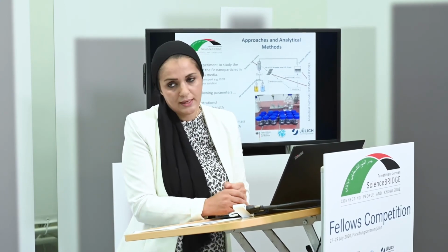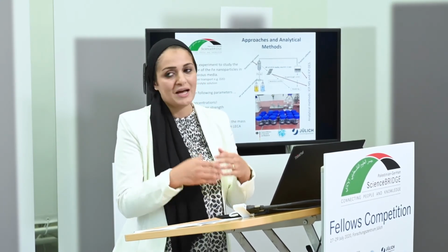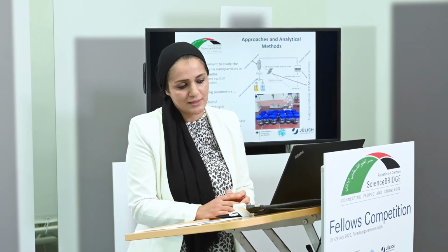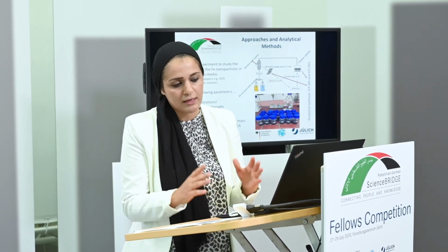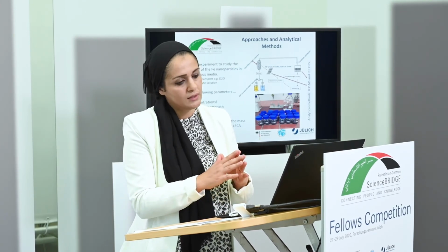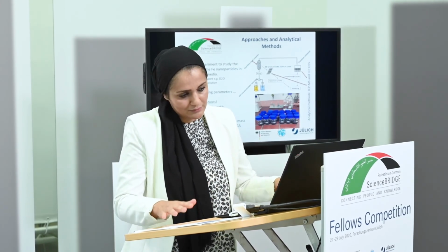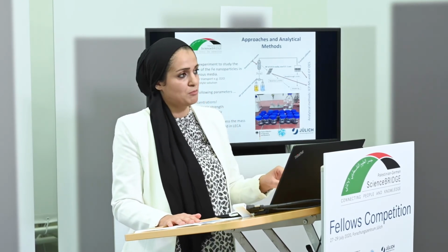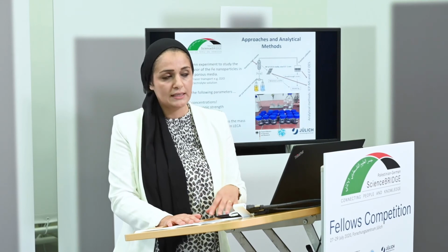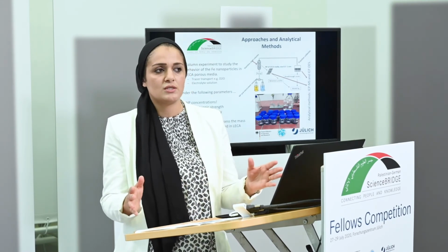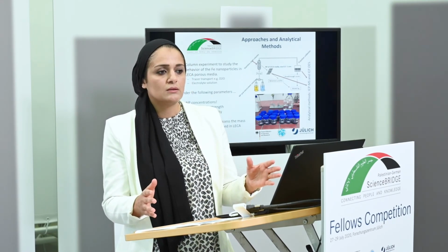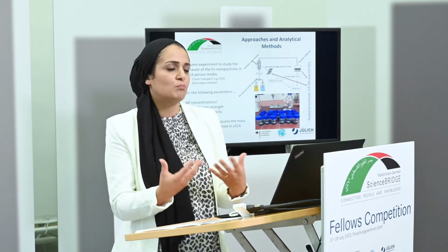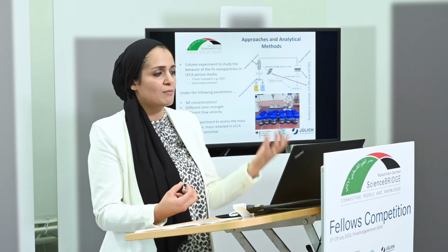Of course, LECA is composed of iron, and I am using iron. This is the biggest challenge, and I spent maybe 6 months figuring out how to do this. We came to, I would say, a delicate procedure to do a batch experiment without digesting the LECA itself, because if you digest it, you will get iron both from the LECA and from the nanoparticles.